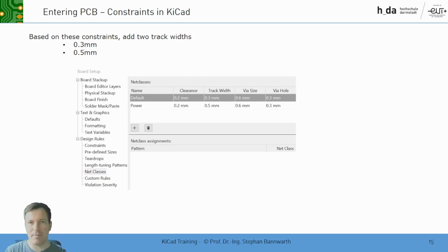Like this, if you have bigger boards with different net classes, for example, high-speed signals, low-speed signals, power and high power, then you can define here already, based on your calculations, what should be the ohmic resistance of your trace, approximately the minimal width you need to route the signal. You can predefine these classes here in KiCad.